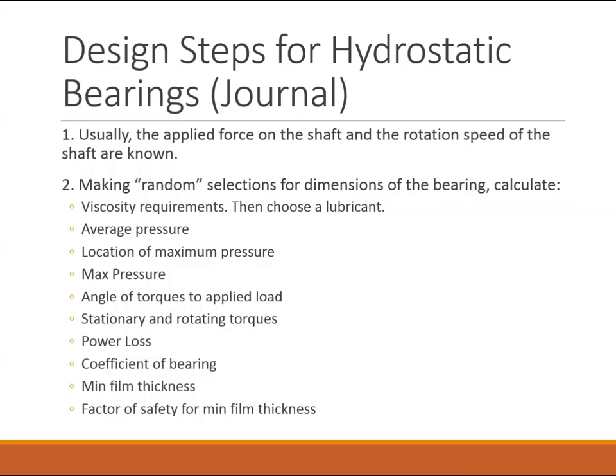So just so you know where we're going, that gives me the minimum film thickness, and finally I can have a factor of safety to make sure that my film never gets too thin and we don't wear out the part. So this is what we'll do. What I'm going to do in the next few slides is discuss how to find some of these, the maximum pressure, and then in class we'll go through an example where we do all of these steps in a specific design scenario.